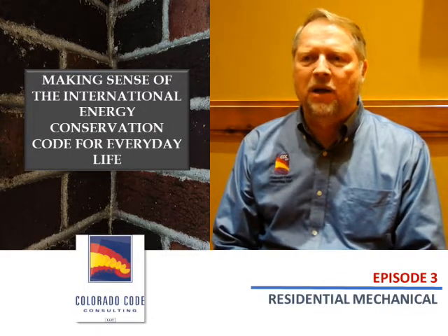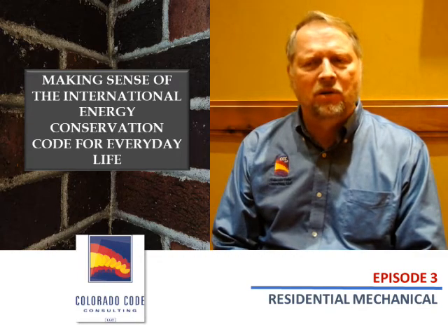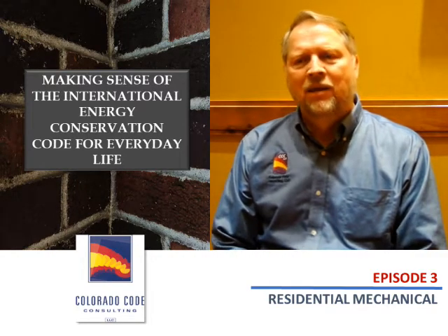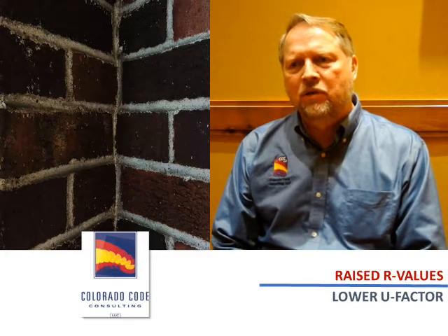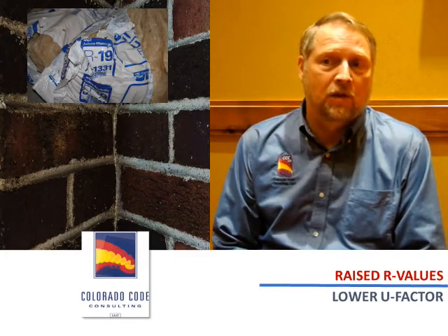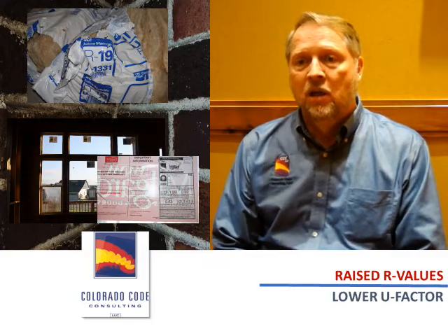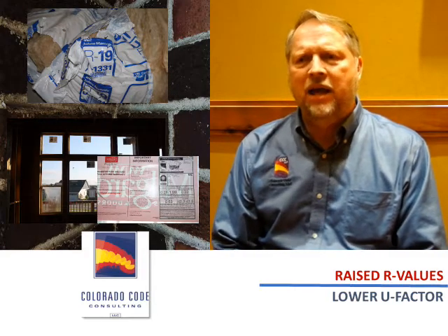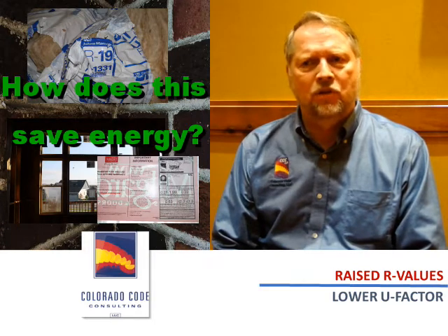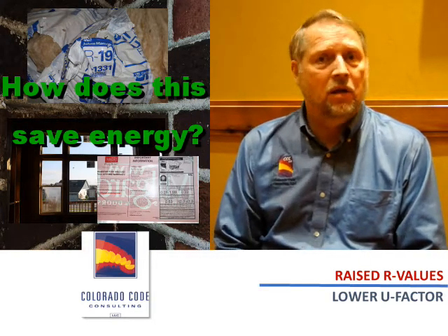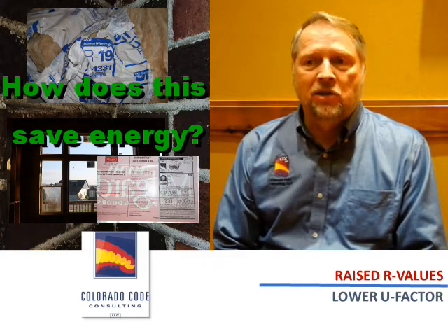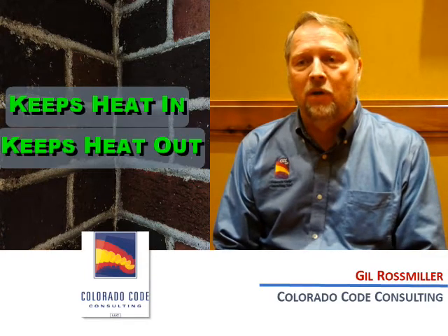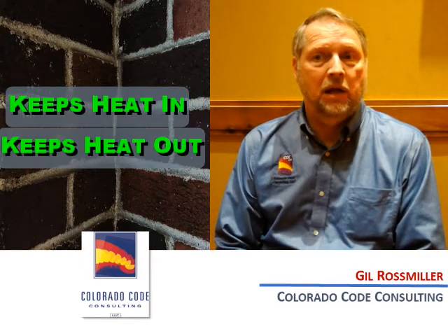Today's episode is about how residential mechanical systems save energy. The last few code editions have increased our energy efficiency by raising R values and lowering U factors, and one may wonder how that actually increases the energy efficiency and saves energy of a home. The truth is that raising R values and lowering U factors in itself actually doesn't save any energy, but it does increase the ability for the building's thermal envelope to keep heat in or heat out.